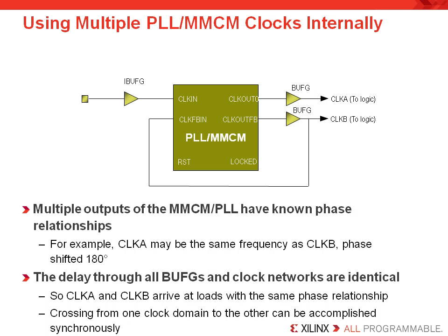So, for example, if the clock output 0 is programmed to be twice the frequency of the clock feedback output, the implementation tools note that the static paths between the two clock domains are constrained by the period of the faster clock. Likewise, if the frequency is the same but the phase is shifted, that is, clock out 0 is advanced by 90 degrees from the clock feedback output, then the tools are also smart enough to constrain the data paths from clock A to clock B to 3/4 of a clock period.